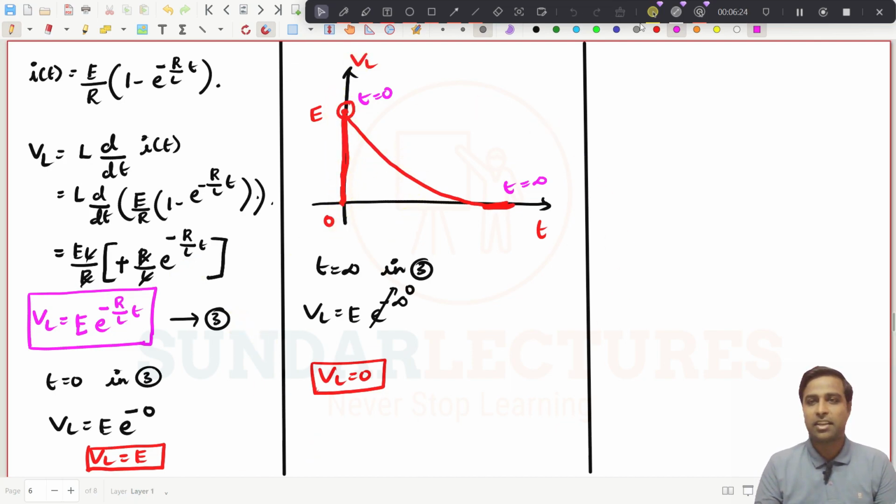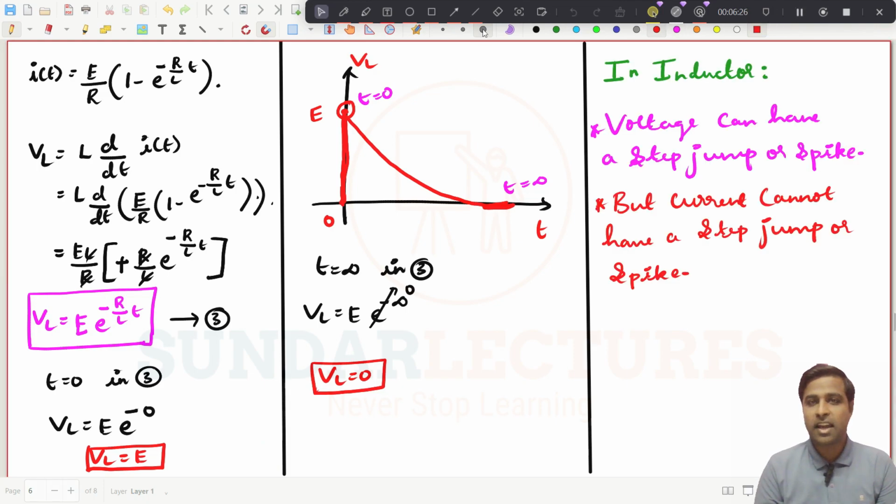So I will just write it down. I have just written: inductor voltage can have a step jump or spike, but current cannot have a step jump or spike. It can increase exponentially or it can decrease exponentially. While retrieving or discharging energy, it will decrease exponentially. But a voltage can have a spike.